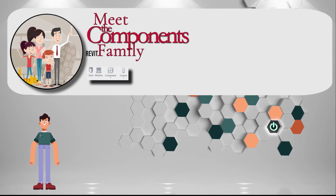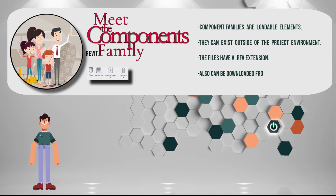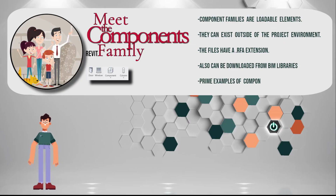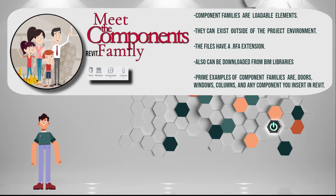To summarize, component families are loadable elements. They can exist outside of the project environment. The files have an RFA extension. They can also be downloaded from BIM libraries or manufacturers' websites. Prime examples of component families are doors, windows, columns, and any component you insert in Revit.